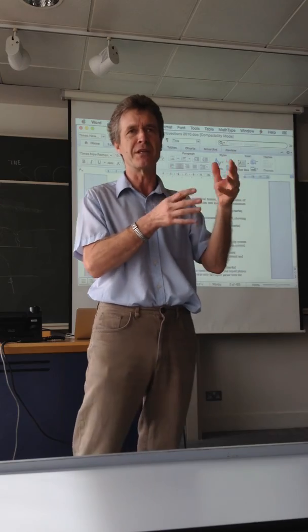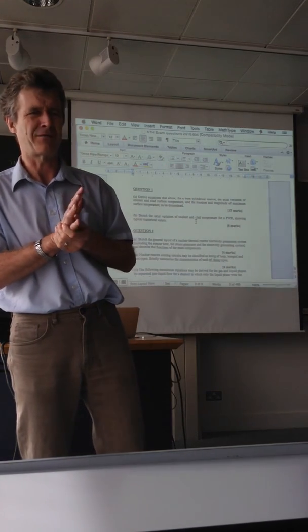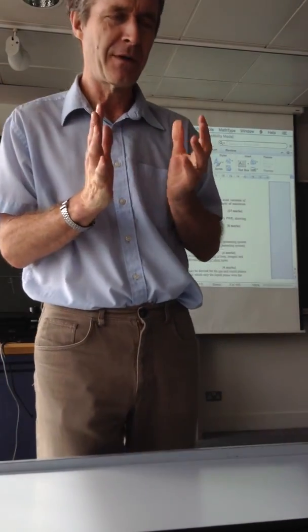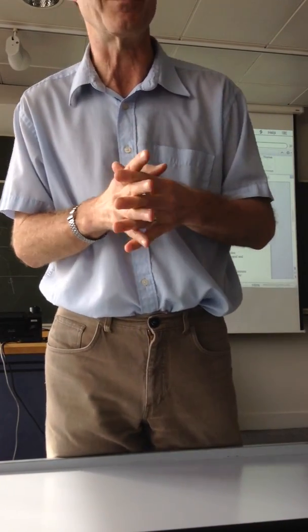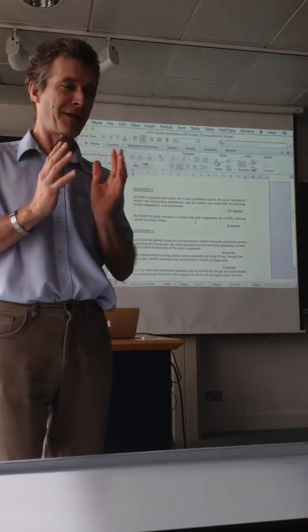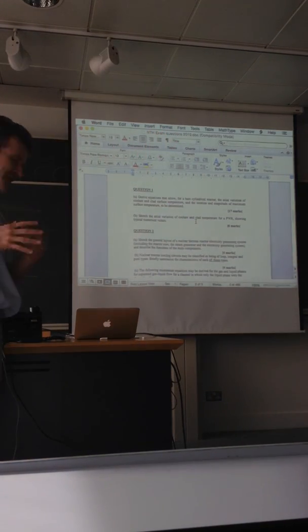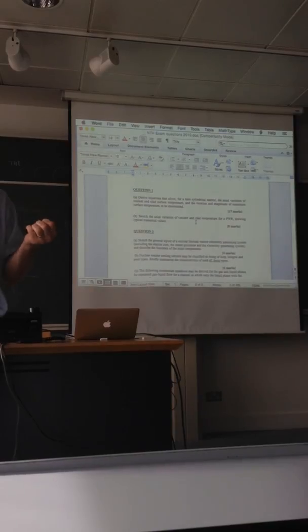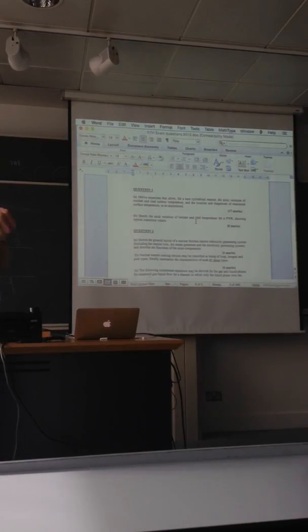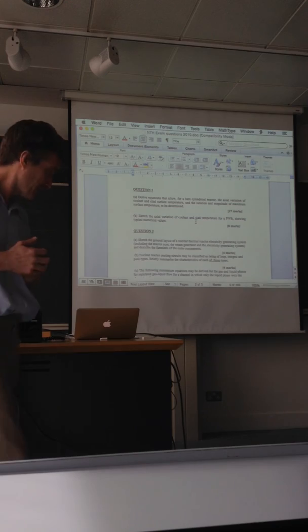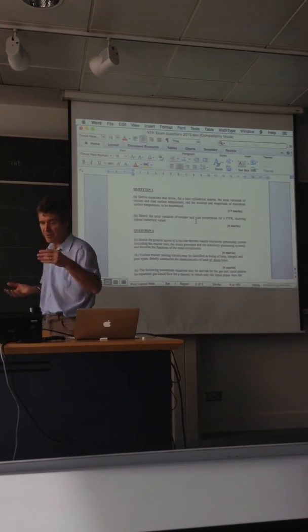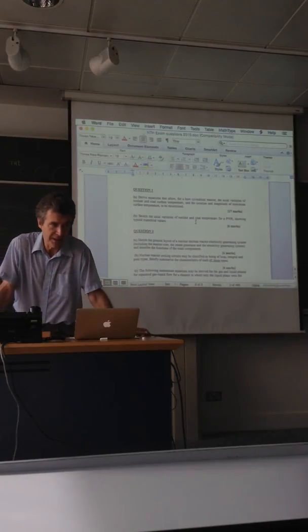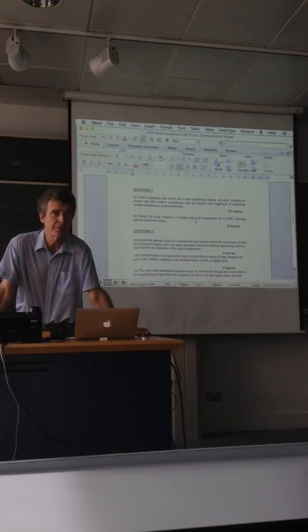So you're not actually looking for a number about the inlet temperature? We did learn that. I'm very pleased if you quote actual numbers. But it's really to give a sense: you need to know where you are in this parameter space, where the engineer is working, because obviously it's very different conditions. Just like the clad delta T, the boundary layer delta T. It's sort of 10 Kelvin, 20 Kelvin for a PWR, and 10 times that for the AGR.